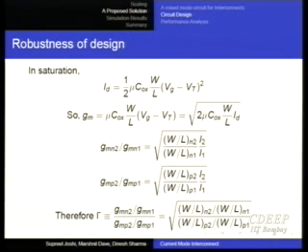Okay? And it is totally independent of mobility, therefore it is independent of temperature. It is totally independent of Cox, therefore it is independent of device to device variation and so on. It depends only on the geometry. That's very good news. Because now, just by controlling the geometry, I can bring gamma as close to 1 as I dare, depending on how controlled my geometry is.